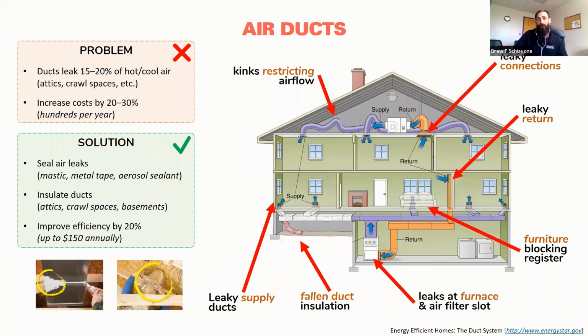But through those distribution systems, with a central system in particular, you can have a lot of leaking air, and other things could account for a tremendous amount of energy loss. So whether you're comfortable working with some of these systems or you hire someone out to check them, you need to make sure that it's all sealed up.